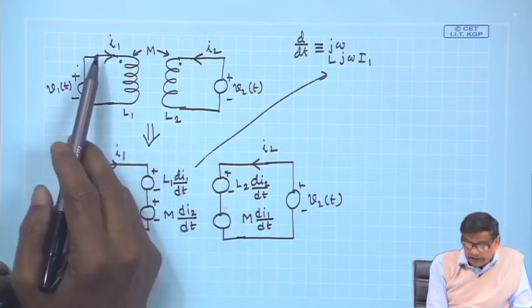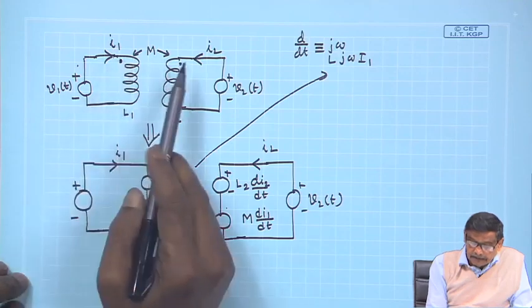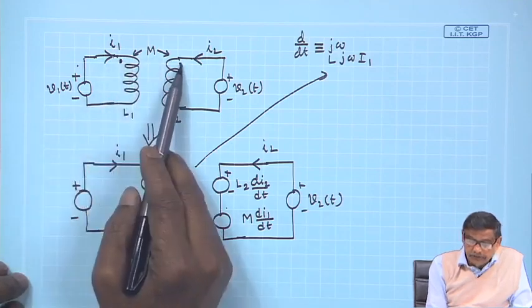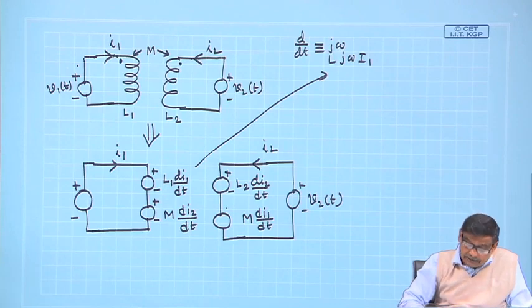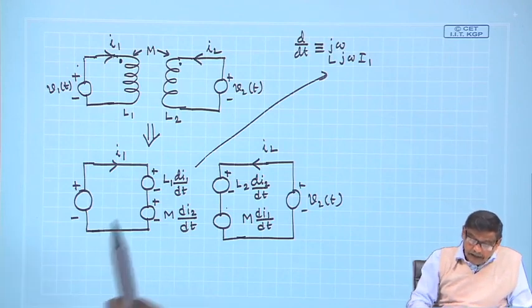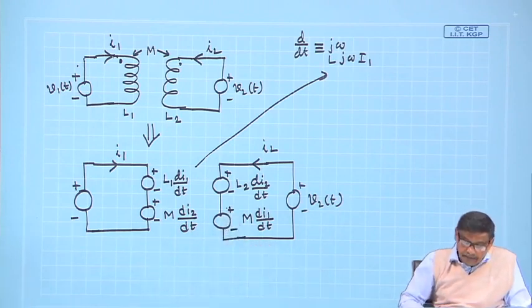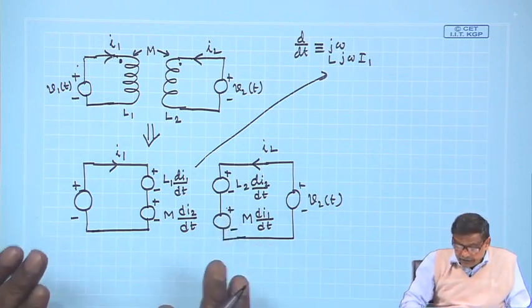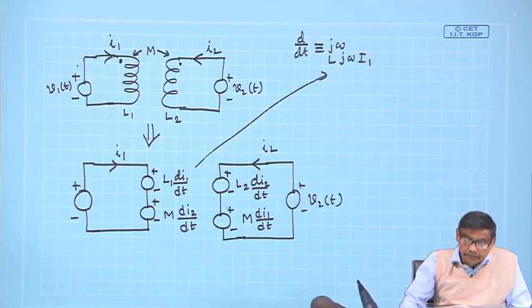Now, see, through the first coil I 1 is entering through the dot, then because of mutually induced voltage in the second coil, it should be M d I 1 dt with upper side plus, that is the thing. So, once this is correctly drawn, then calculations of instantaneous power and from that energy become very simple.